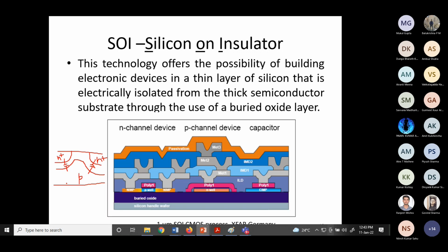Although yesterday we said we don't increase the clock frequency aggressively, we would like to increase it if we can. The reason we don't is that it will increase the temperature of your chip. Now, if we can reduce these capacitances, source with substrate and drain with substrate, that will improve your device performance.